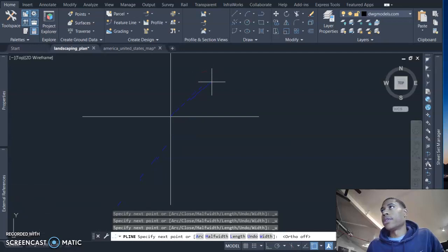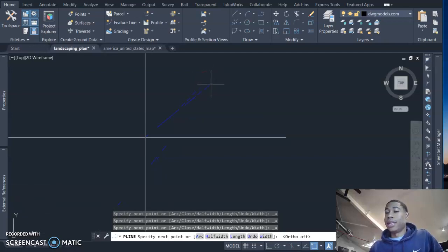So the first thing that you want to do is type out the length that you are wanting it to be. So for this particular example, say we want it to be 100 feet. Well, actually first, I'm sorry, we're going to type in the @ symbol. So hopefully you can see down here in my toolbar that I literally put the @ symbol, and then now we put the length.